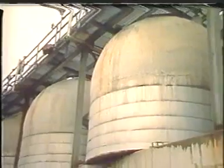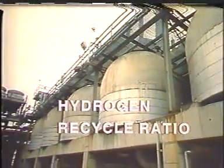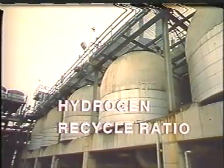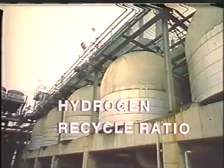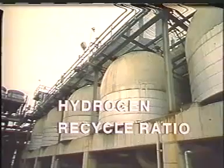Another important operating variable is the hydrogen recycle ratio. This is simply a measure of the amount of hydrogen in the recycle gas compared to the amount of hydrocarbons being charged to the unit. Recall that hydrogen must be mixed with the feed to minimize coke laydown on the catalyst.